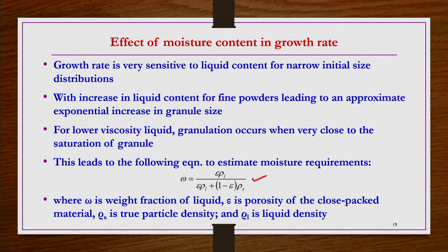If you take more than that, a loose slurry kind of material may form, and then granulation may not take place. If you take much less than this quantity of liquid, then again proper granulation may not take place; only partial granulation may take place. So that is the reason the effect of moisture content also has a very strong role on the size enlargement growth rate.